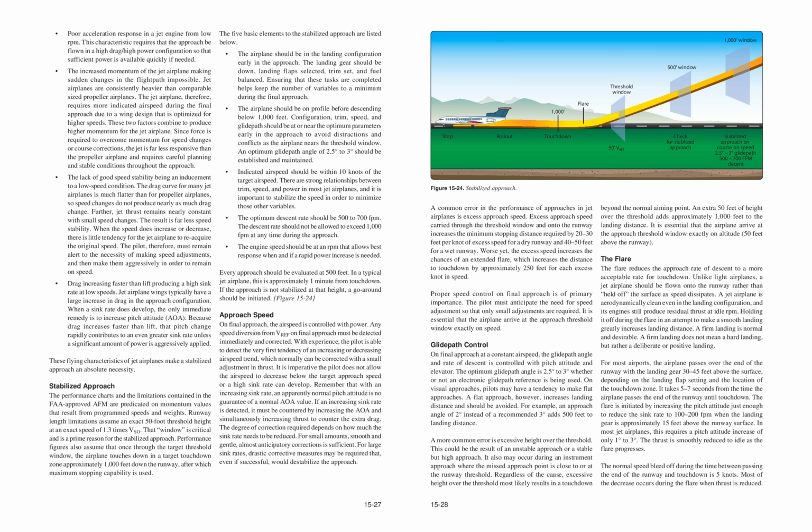The degree of correction required depends on how much the sink rate needs to be reduced. For small amounts, smooth and gentle, almost anticipatory corrections are sufficient. For large sink rates, drastic corrective measures may be required that, even if successful, would destabilize the approach.